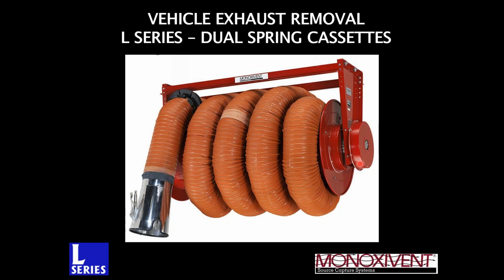We added a second spring cassette. Now this second spring cassette, it doesn't double the weight capacity, but it increases it enough that we can handle the majority of 8-inch applications and keep you in the spring hose reel family. So theoretically, I can do up to 44 feet of 8-inch diameter hose wrapped completely around this drum. I say theoretically because in reality, if I need 41, 42 feet of that 44 feet of hose, by the time I pull that much hose off of the reel, my spring tension is so tight, I'm fighting it every step of the way.